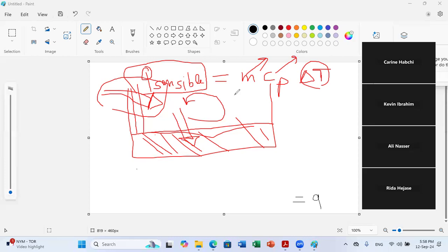So if we talk about the Bekaa region, for example, this will be very efficient because you have very high average temperature during the day and relatively low temperature during the night. So during the night, your thermal mass will restore back the energy stored in order to keep the temperature within your environment acceptable, and it will fluctuate in a very reasonable range.